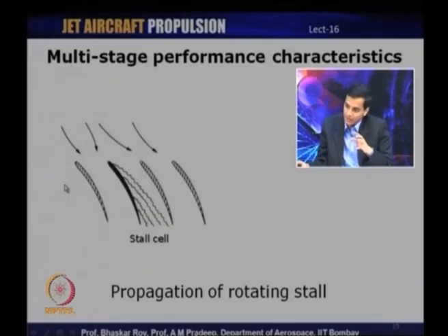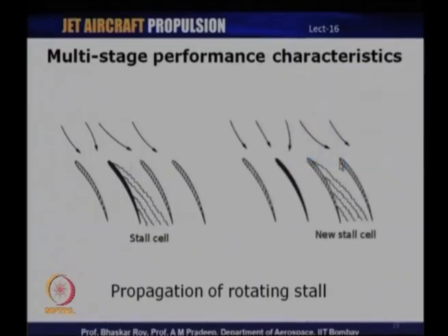So, there is also a relative motion here, the blades rotate, and because of this the non-uniformity now progresses and moves towards the adjacent blade, causing the adjacent blade also to now stall. Now, as this blade stalls, it unstalls this particular blade which was earlier under stall, because the flow is now deflected in this fashion here, and also because of the rotation of the blades themselves.